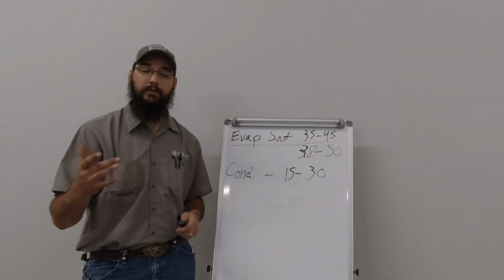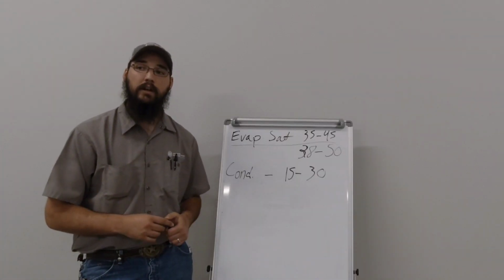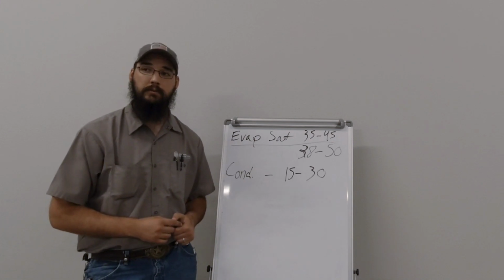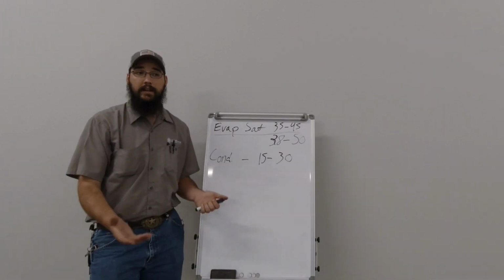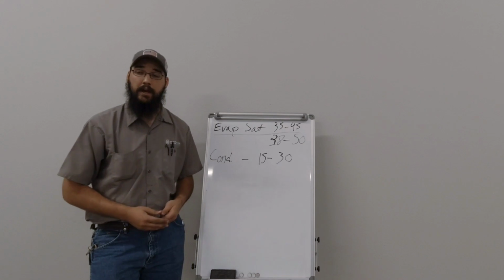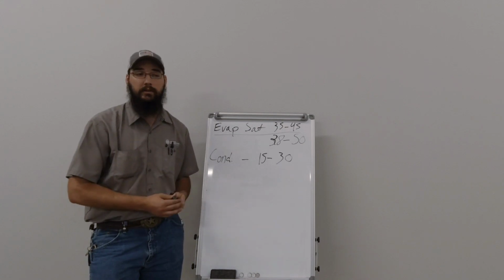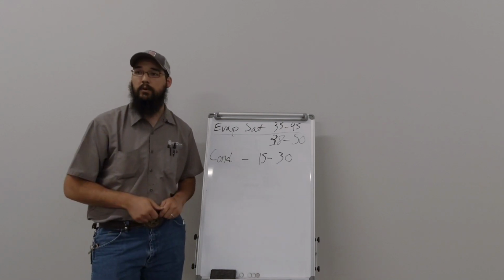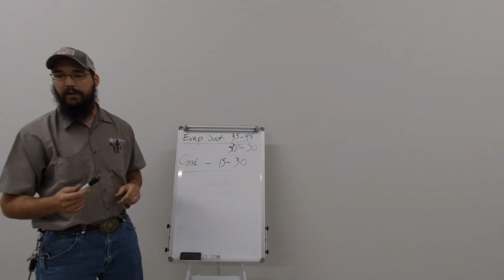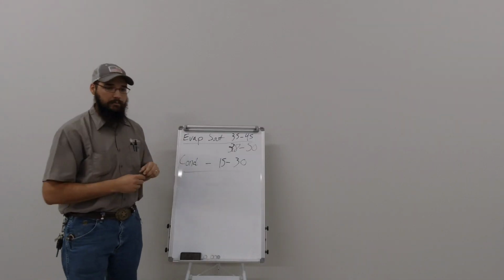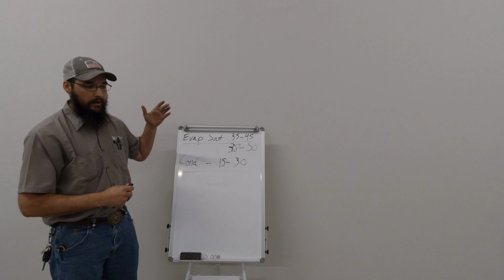Because if you look at the wet bulb it's asking for, it is the indoor wet bulb at the return. Because the latent heat is still a heat load and it does impact the indoor coil. It does not impact the outdoor, but it does the indoor. And we'll get into that more as we go. Superheat and subcool, obviously they play a big part in this.